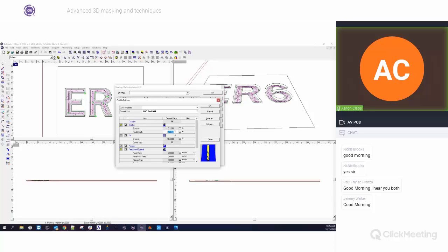So I want it to go 0.125 inches deep, but I need to tell the software that, hey, by the way, there's another toolpath that I already processed that milled the surface down a little bit. So the 0, 0 is no longer at 0. It's actually down a little bit. So that's why I put in 0.125. I milled down the surface of that cutout at 0.125 inches. So that's why I'm putting that here.